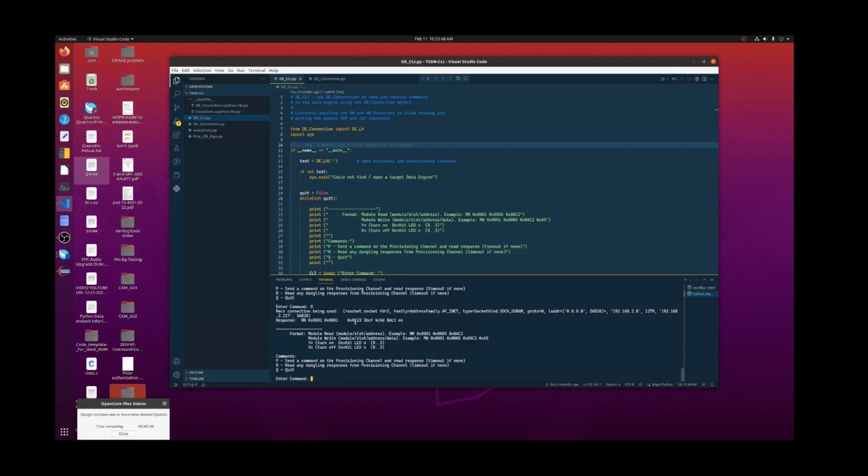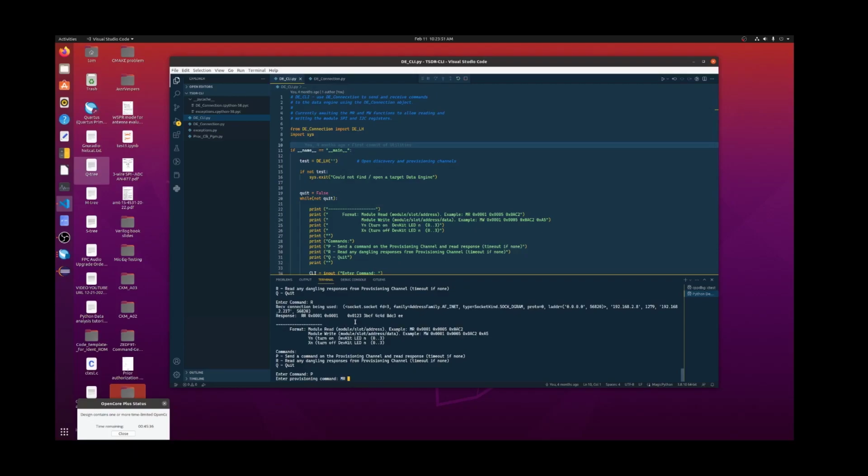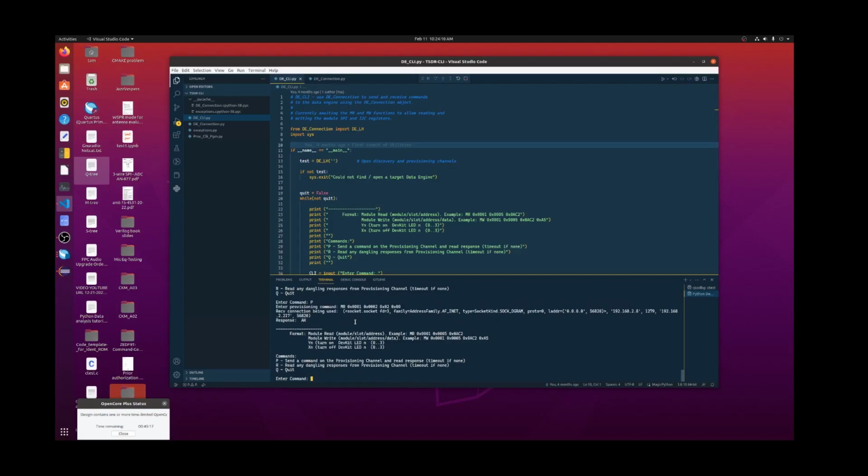We can also issue a provisioning command, module read, the receiver module, 0x0001, and the interface number 2 is the SPI interface. And we want to read on that SPI interface the address number 2 on that particular interface. And if we read the response on that, we get a 0x55, which correctly identifies the Analog Devices chip is responding to the SPI command. There are a few other commands here, but at this time, we'll leave it at this.